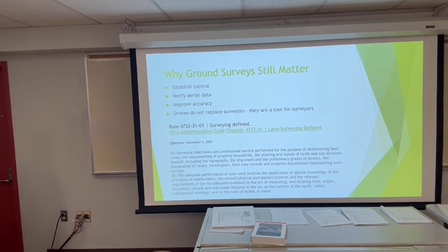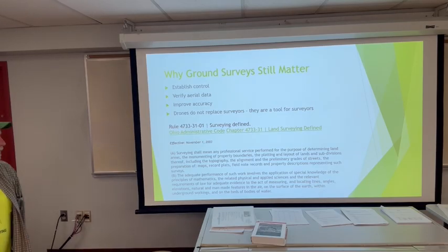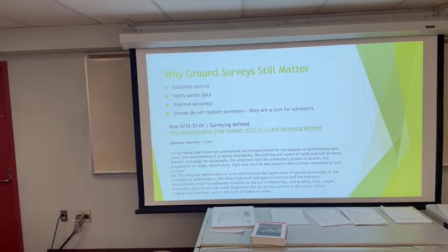Ground surveys still matter because that is going to be the main way of establishing control. Like I was talking about a little bit earlier, the photo identifiable points, some random check shots to verify aerial accuracy and to help improve accuracy. A lot of people seem to think sometimes that drones are going to replace the surveyors. They're not. They need to be looked at as a tool for surveyors.